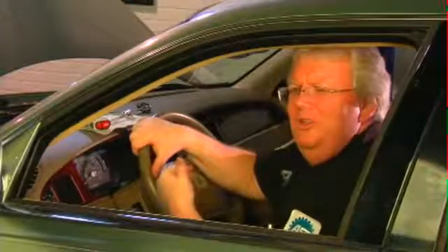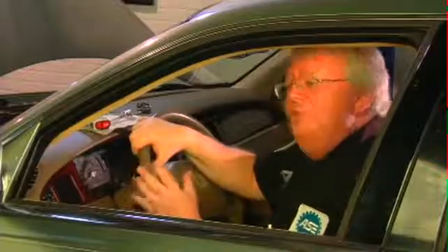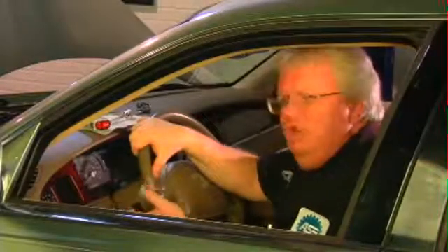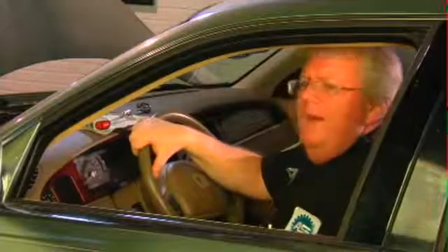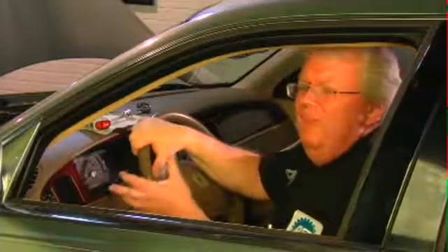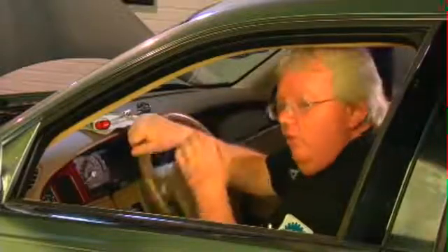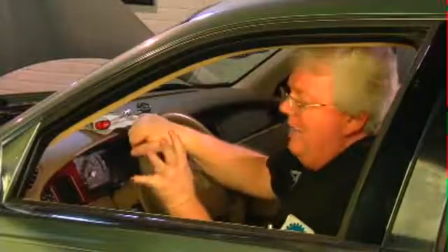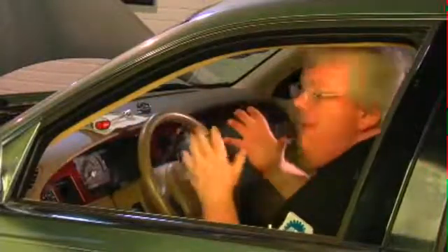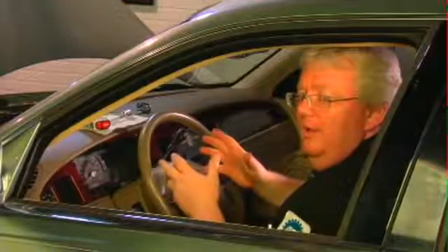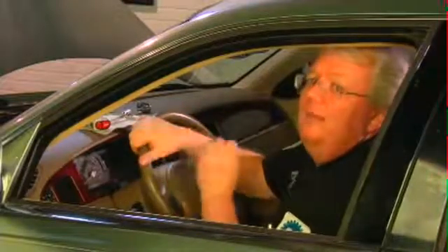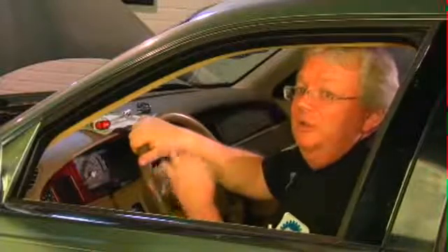Why is the vehicle in the shop? It's got a problem. Could it have multiple problems? Sure. Could somebody have been monkeying around with something? Or could some wires be chafed in the steering column? You may have some 12-volt hot all the time power, and certainly there's ground because there's metal in the column. If those two wires were to, and it would be a very rare instant, but if they were to short together while the airbag was powered up, then it could deploy the airbag right at an inopportune time, which could result in injury or even death to you, the technician.